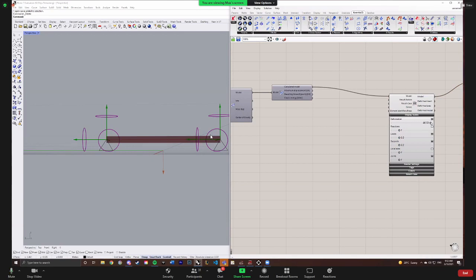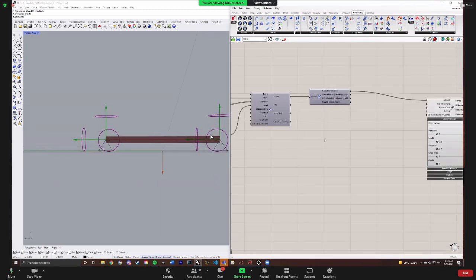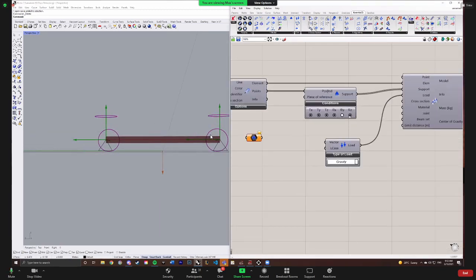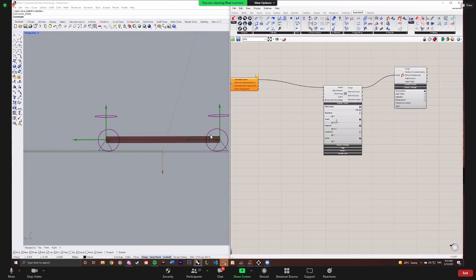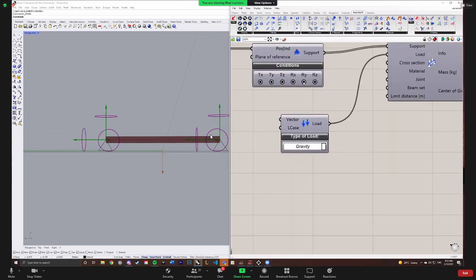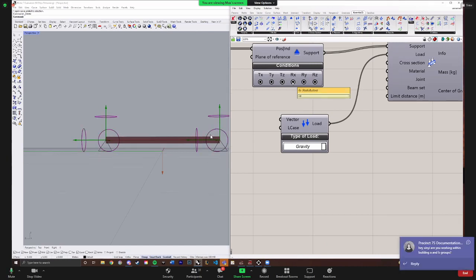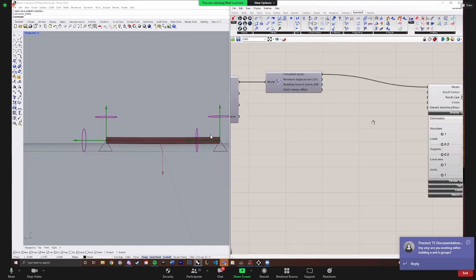Can you change it to be a pin joint rather than a rigid one? I think it's just a really small gap. Just like that one there? Yeah. Can you turn that off and on? No, turn on. It looks like you've drawn it in the Y direction. Turn on the X axis. There you go. Yeah, you can see it move slightly. There's a tiny one there. I think it's just tiny.